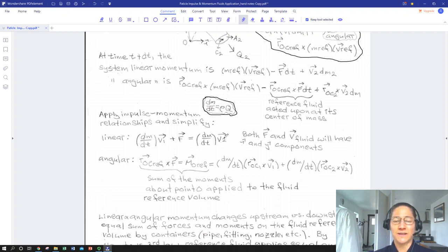and then the mass flow times the exiting velocity. So we don't have to get some crazy force strain gauge out there. If we have some kind of flow rate, we know the area, we can easily measure these two velocities. We can measure it through flow meters or other types of methods. So upstream, downstream velocities, we know what the mass flow rate is, we know what Q is and the density. We can calculate what force we are going to have on that elbow and in what vector direction.